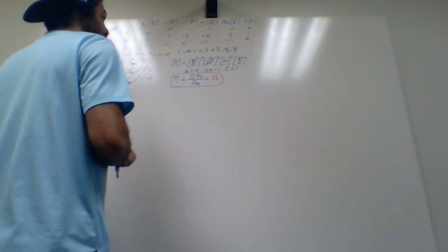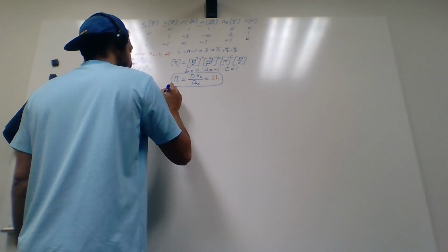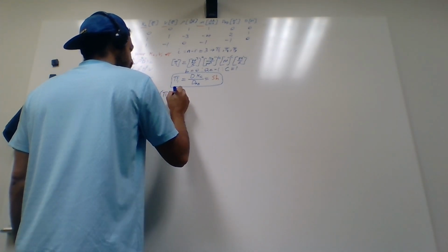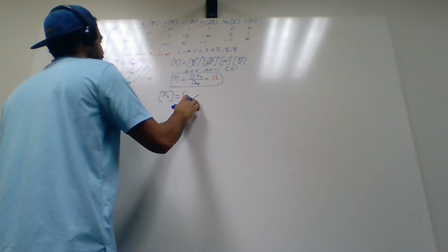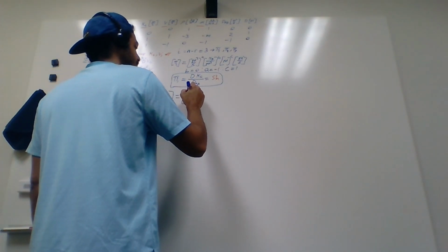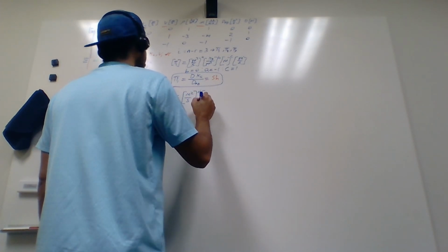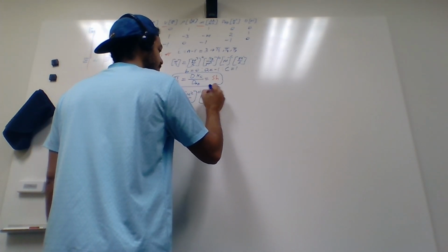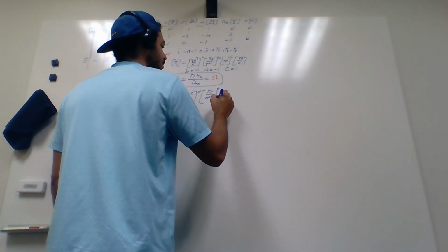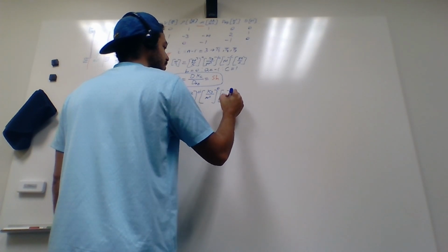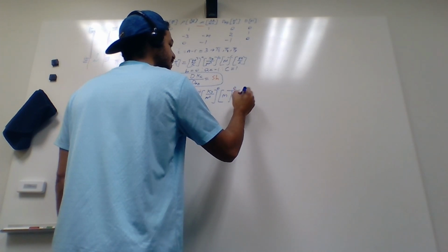Now we're going to look at pi 2. So the units of pi 2 are going to be equal to the diffusivity, meters squared per second raised to the D, times the density, kilograms per meter cubed raised to the E, times the diameter in meters raised to the F, times the velocity, which is meters per second.